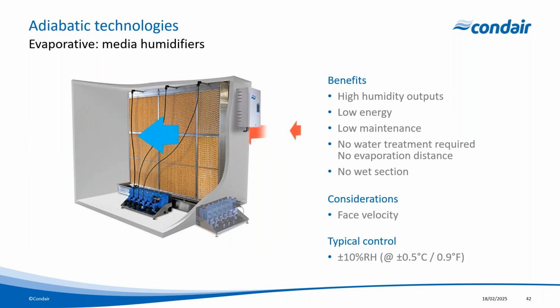So just a couple considerations here when you're looking at an evaporative media system will be the media velocity and the typical control accuracy. So the media velocity, or the velocity onto the media, will have an impact on the efficiency of the system. So when we talked about that enthalpy line and how far up that enthalpy line we can go, this is where that comes into play. So it's the efficiency of the evaporative system. How much water can we evaporate into the air?